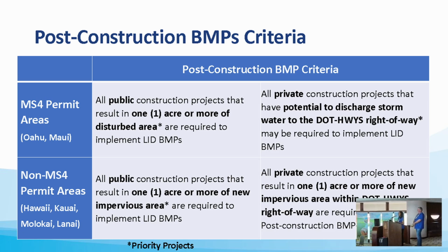So wherever there is potential for additional pollution or a discharge to a central water body, DOT has discretion to require post-construction BMPs regardless of this criteria. So if your project falls under priority project criteria, DOT may ask you to do either LID or post-construction.